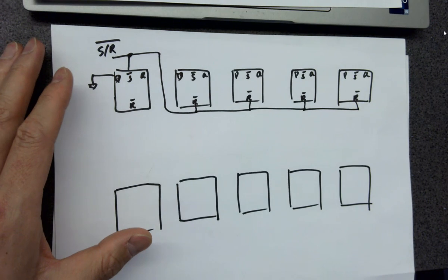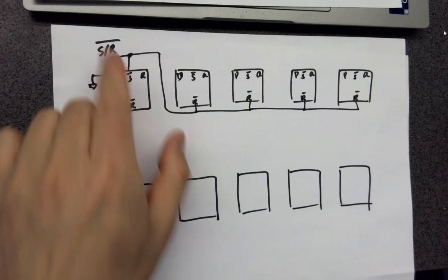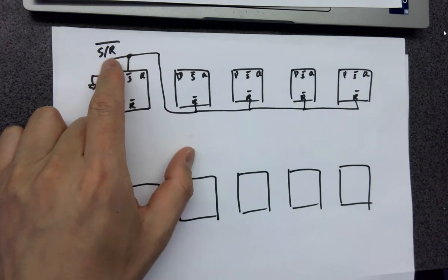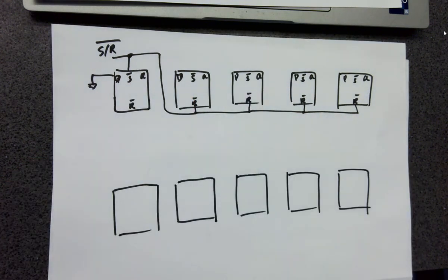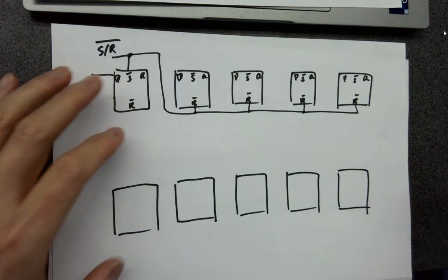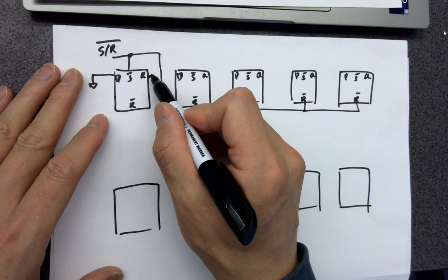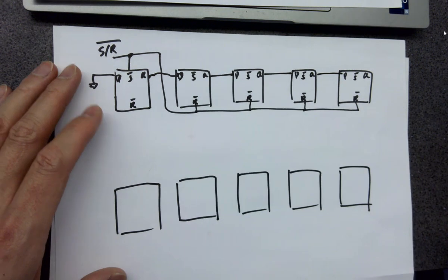Okay? So you need a clock cycle. You need 1 clock cycle doing the reset, which means you need the zero pulse, a dip over here to reset it. So the first one becomes 1, all the following ones become 0. Just the 1 dip, 1 clock cycle at the very beginning of each conversion. And definitely it's a serial in, parallel out. So all the Q's need to be shorted to the D's of the next stage.